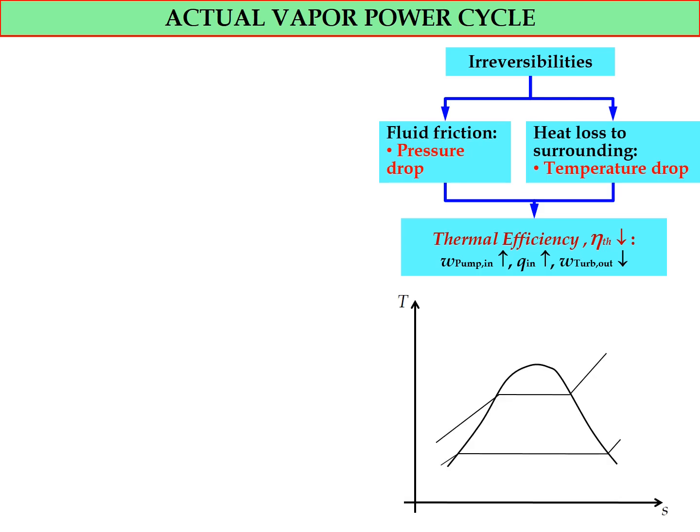Okay, so this figure shows the T-S diagram in order to show the difference between the ideal Rankine cycle and the actual Rankine cycle. The ideal Rankine cycle shown in this T-S diagram is presented by the red color line cycle, starting from state number 1 prime, 2 prime, 3 prime, and also 4 prime. And the second cycle, shown by the black color dash line cycle, is the cycle for the actual Rankine cycle. So we can see here the difference between the ideal Rankine cycle and the actual Rankine cycle.